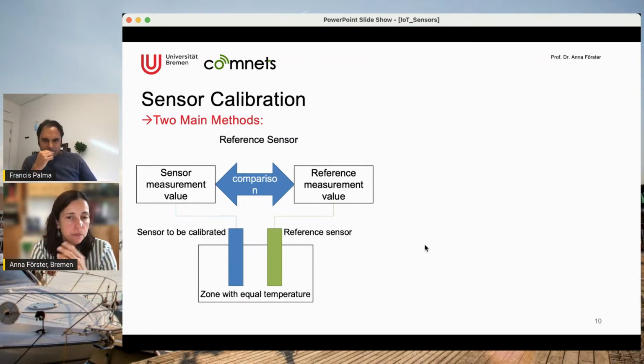This is typically something which the manufacturers already did for you, and you just have to make one single measurement and push the line up or down. Okay, so the line itself, even if it's a complex curved line, is already defined for you by the manufacturers. And you only have to recalibrate your sensor in terms of only one point, which pushes it up and down. But this is also part of the specification of the sensor of how to calibrate it.